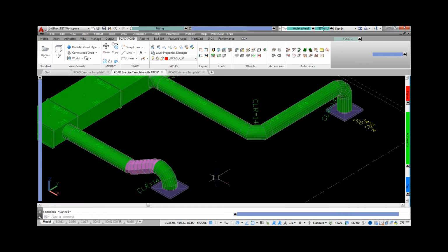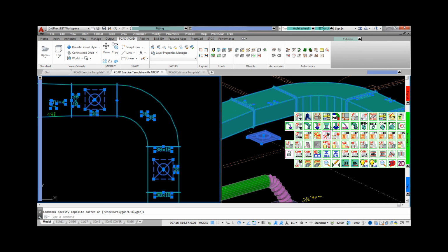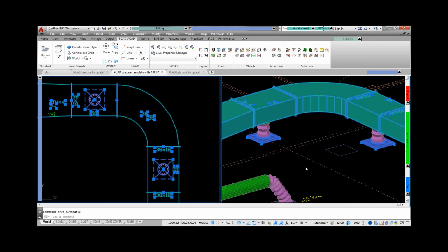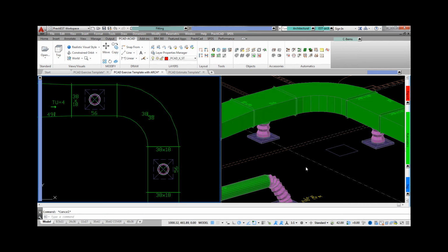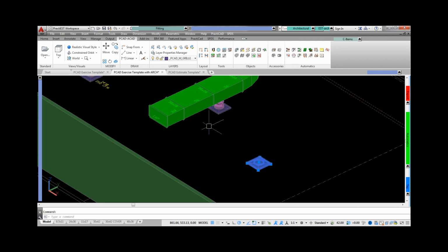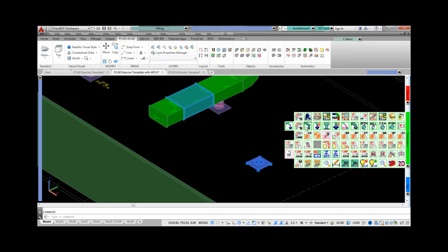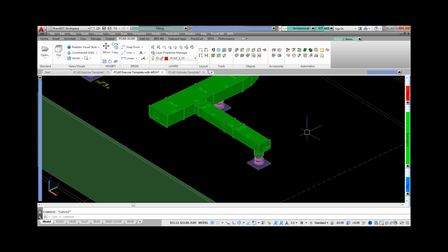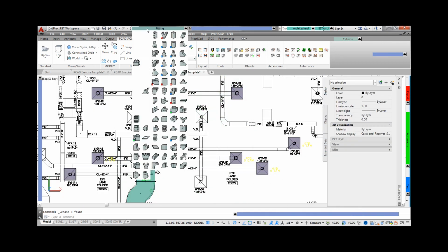Dropping it down to some GRDs lying under the duct has never been easier. Just window select and route. All the parameters you need are there, including min, max, flex lengths. Here's a route that requires a boot tap first. It runs over a grill's neck, then it stops, end caps the run, and then drops down to connect with a spin collar and flex.